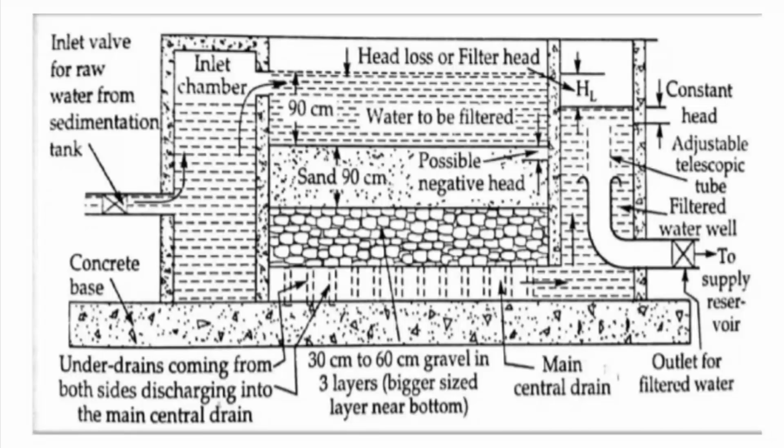So we have to wait for some more time for all these mechanisms to develop in the filter media. We have to wait for 36 hours to restart this filtration tank back to the working condition. Because of this reason, we have to provide a standby filtration tank for continuous operation of the water treatment system. This is the normal working and cleaning of a slow sand filter.